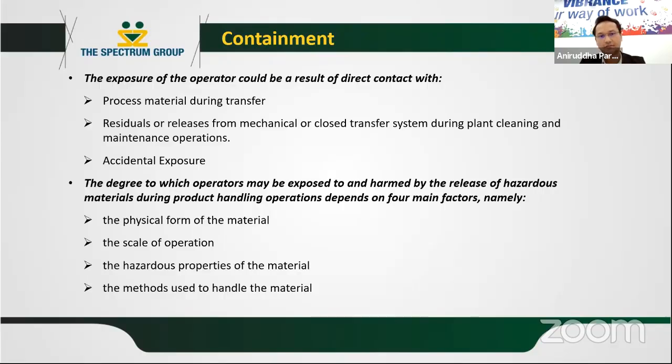For example, if it's in liquid form, there's actually no exposure chance, or the risk of inhalation drops. When it comes to powder form or flakes, it can release dust into the environment which the operator can inhale, so the risk is definitely much more.